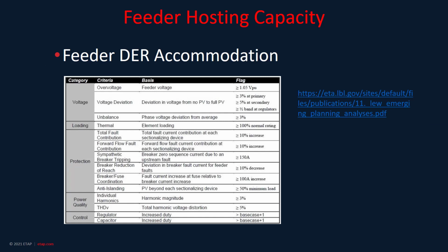Continuing with feeder hosting capacity and feeder DER accommodation: how much DER power a feeder can accommodate without violating the criteria. The purpose of feeder hosting capacity analysis is for studying the impact of distributed energy resources, or DER, to the distribution systems. The impact is unique to individual distribution feeders and is based on certain issues ranging from voltage, loading, power quality, protection, and control. ETAP will provide integrated solutions for DER evaluation and approval.